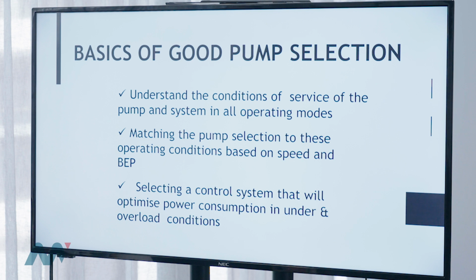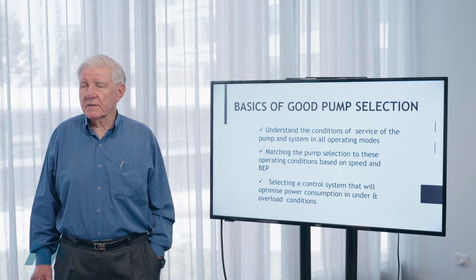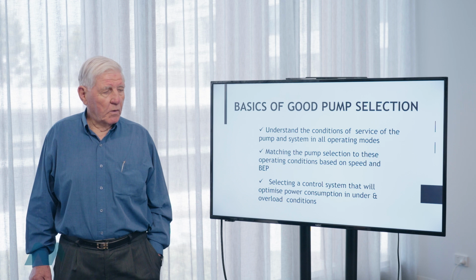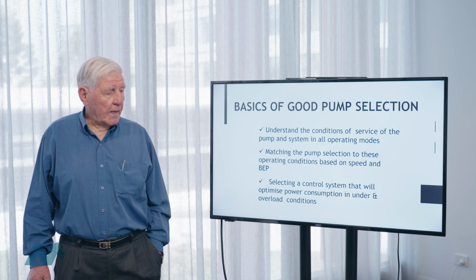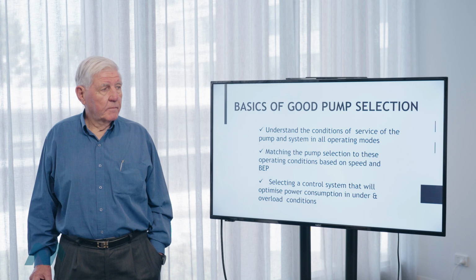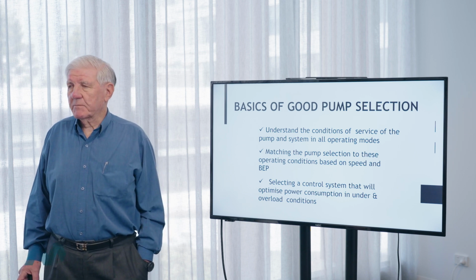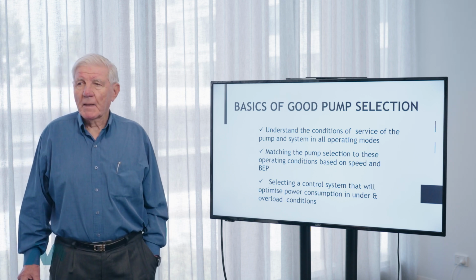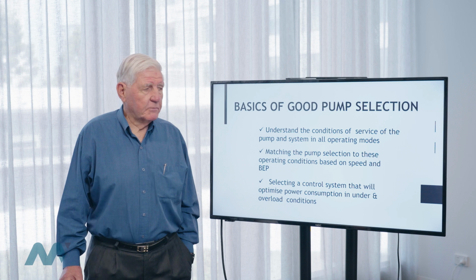And then you need to understand how the control system is going to operate on that pump so that it will optimize power consumption in both the operating situation and normal under and overload conditions that the system might produce. So those are the steps that you need to go through before you can actually make pump selections.